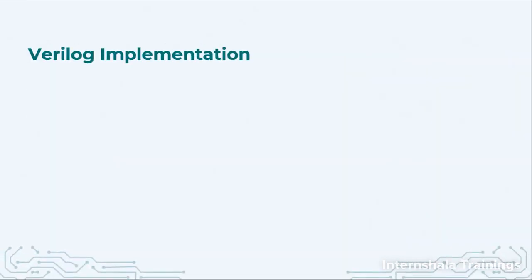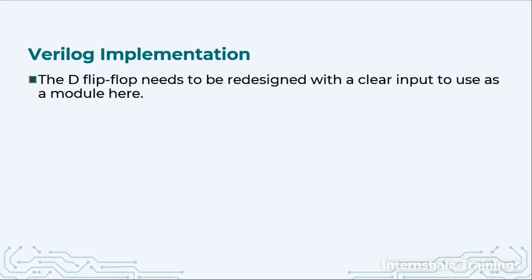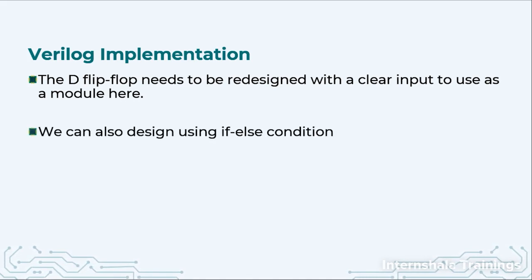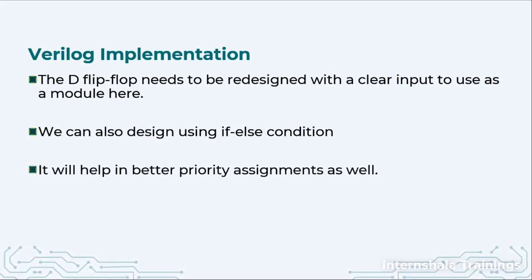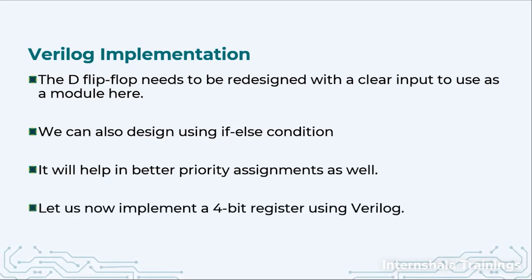Now, let us talk about the practical aspect. The D flip-flop that we had will not work. We need to redesign. We need to add that clear input as well in the D flip-flop. We can also design the same using if-else conditions. So, using if-else conditions, you can set the priorities very clearly. Now, let us design it in Verilog.